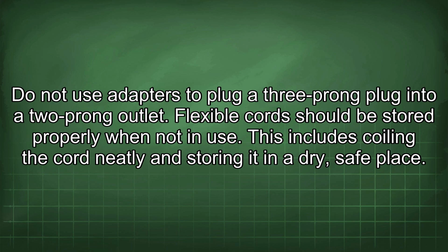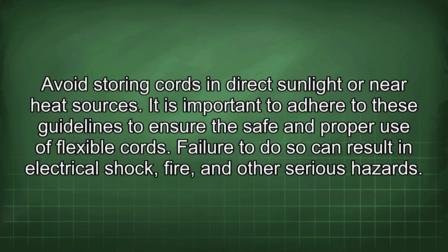Flexible cords should be stored properly when not in use. This includes coiling the cord neatly and storing it in a dry, safe place. Avoid storing cords in direct sunlight or near heat sources.